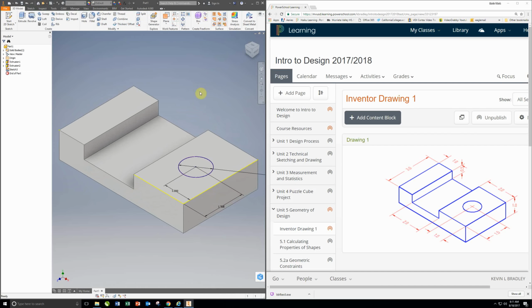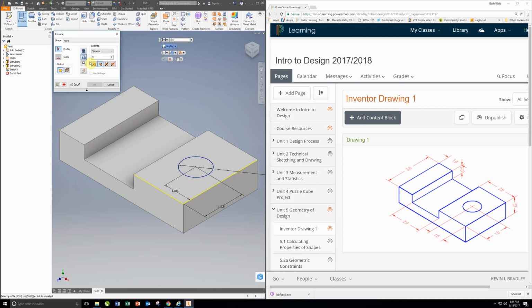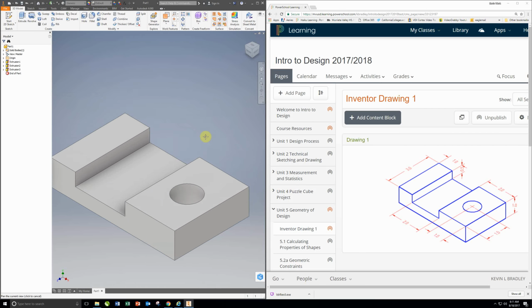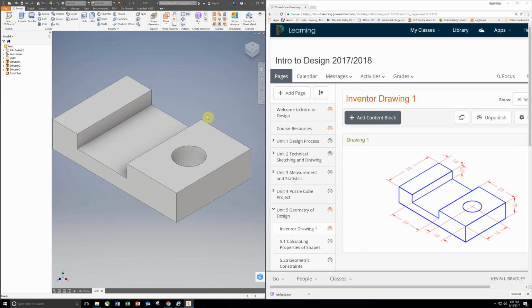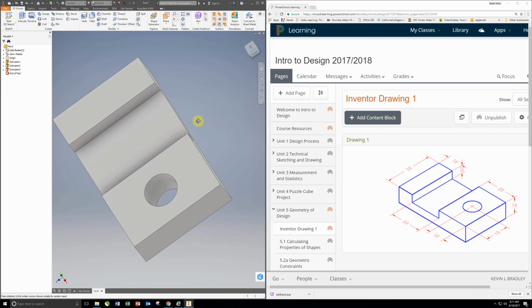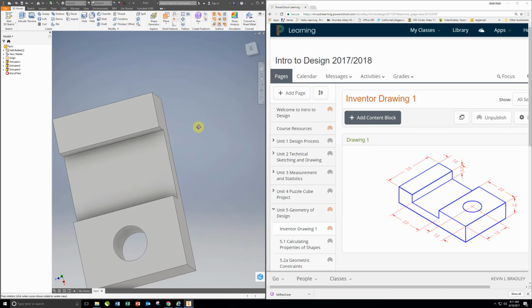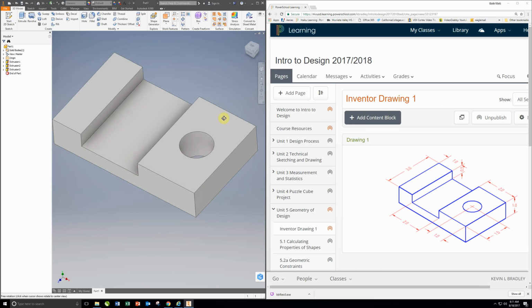Finish sketch. And again, we need to extrude cut this. We're going to remove material. So here's extrude, here's cut, and we have to select the profile, and we just need to go all the way through and click OK. And now when I hold down Shift and my wheel, again I'm holding down Shift and my wheel, you can pan around and you can look at this part on all of the different sides.